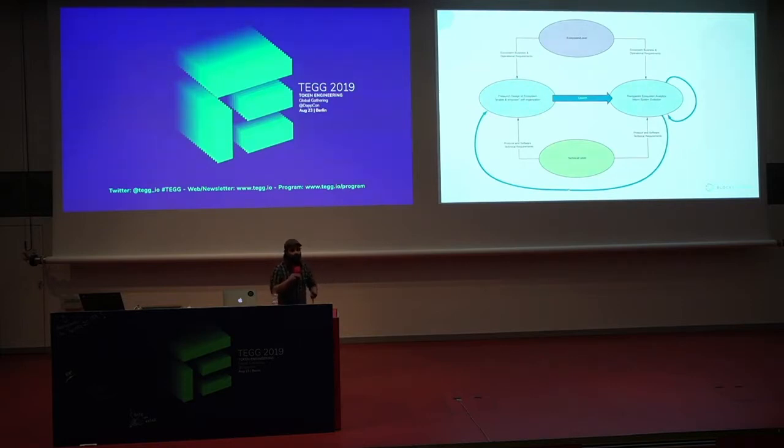And actually in the robotics literature, this is called system identification. If you have a proper differential representation of the way the system evolves, even when there's a bunch of stuff that you don't know, you can actually learn the stuff you don't know. It's gray box modeling. You have a white box, this part works like this, a black box, someone doing something we don't understand, and some data about the whole system. It's a more advanced version of autoregression involving structural dynamics under the hood.